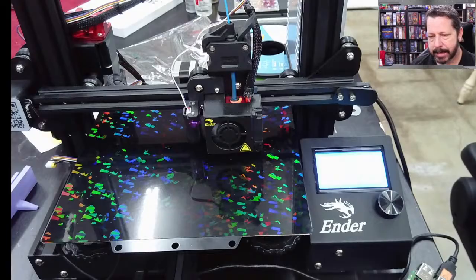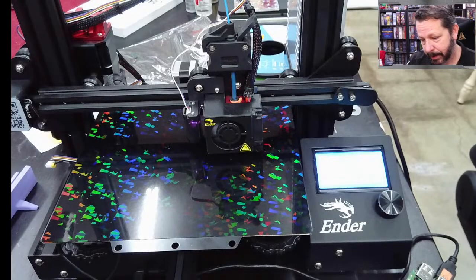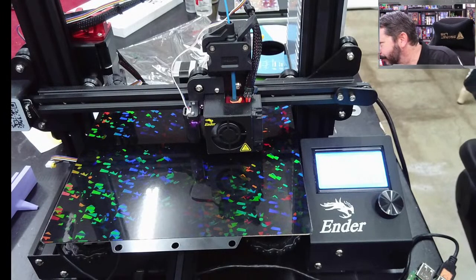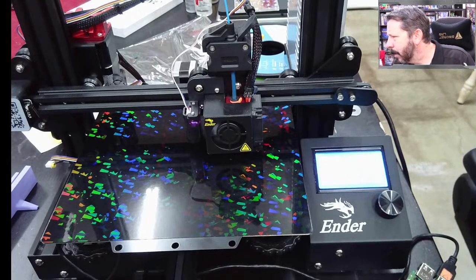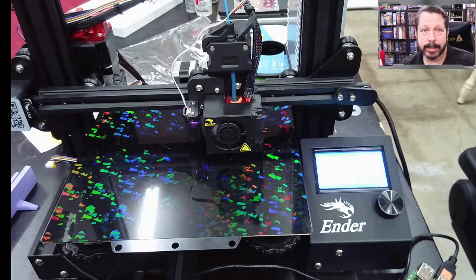Now that I'm seeing this, I do remember that this was a problem. I think in the printer file itself, it is set to go down to 50 degrees on the bed, and so it's having to cool down. Oh, on the preloaded temperature, you may have to make your own temperature tower then, because it doesn't have a raft, or you can't add a raft to just G code, as far as I know. I guess you could, like you could cut and paste, but that'd be hard to do. It'd actually not be as simple as cutting and pasting.